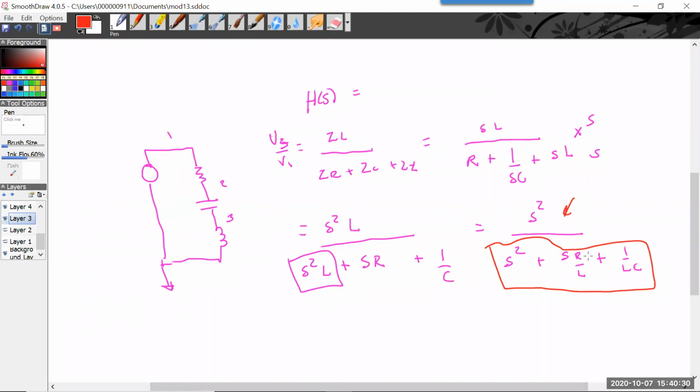If you were to do this in pole-zero format, and S were headed towards 0, if I set S equal to 0, this is 0, and then as S heads towards infinity, these cancel out and it flattens out. So it's a high pass. Now, Bode plots never go to 0, but it's a high pass. And all I did was move this around.